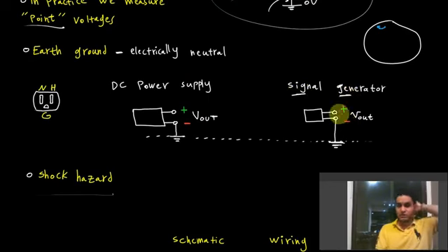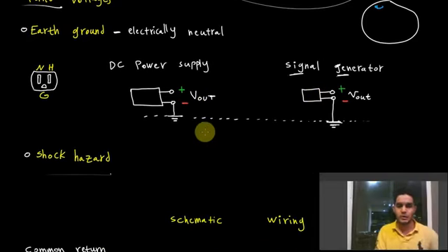Now suppose you were to use these together, you would need to bias an amplifier with the DC power supply, and test the input with a small AC signal and see what the output is, for example. That's something you would do in a typical application. You're going to connect the 3-prong connections of neutral, hot, and ground for both of these devices to the wall outlet.